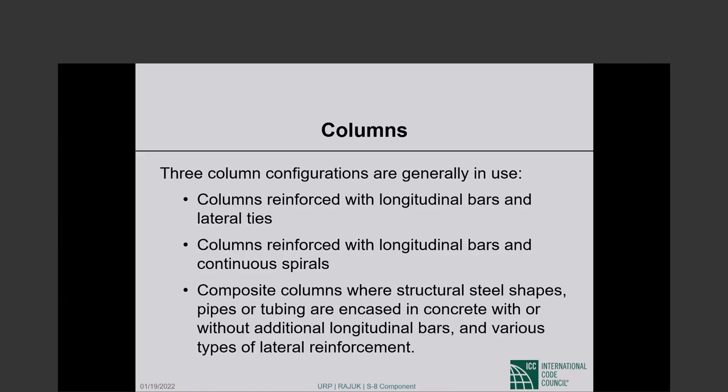this term tie, stirrups, hooks, all of that, I think will be, anyway, next week I will do a session or part of a section on non-seismic detailing of concrete, where those terms will be very clearly defined. But generally speaking, most people are familiar with column ties. So that's number one. Number two is columns reinforced with longitudinal bars and continuous spirals.